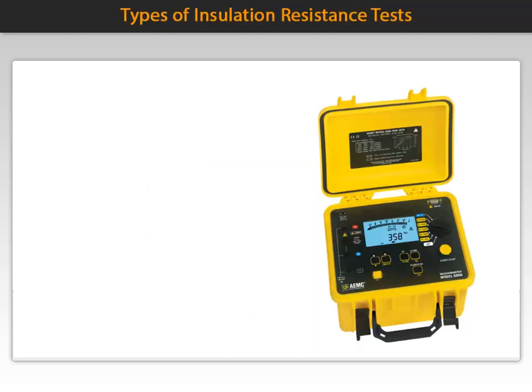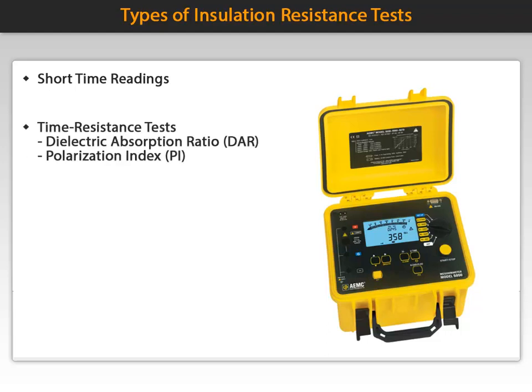There are three basic types of insulation resistance tests. Short time readings usually are 60 seconds in duration. Time resistance tests, which include dielectric absorption ratio, or DAR, or polarization index, or PI. Lastly, there are step voltage readings, which are mostly used for DC overpotential testing and can be used at insulation resistance test values. We'll spend more time on each of these.